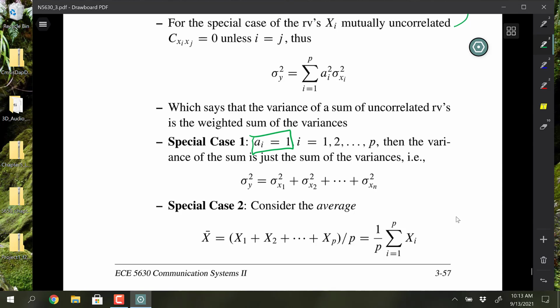So you'll want to form some sort of a weighting, right? When you combine pieces of information together, you want to emphasize the ones that have the lower variance and de-emphasize the ones that have the weaker variance. In diversity combining, that's called maximal ratio combining. There's a name for that, MRC. And so what I had to do to help accomplish that MRC was also come up with a side algorithm that would estimate the signal to noise ratios on each of the channels, so that way you can optimally combine them.